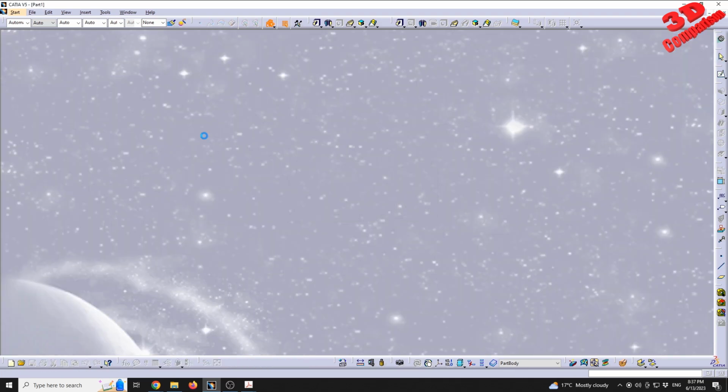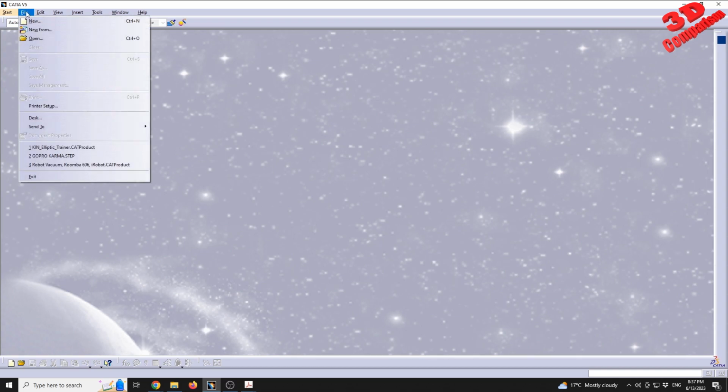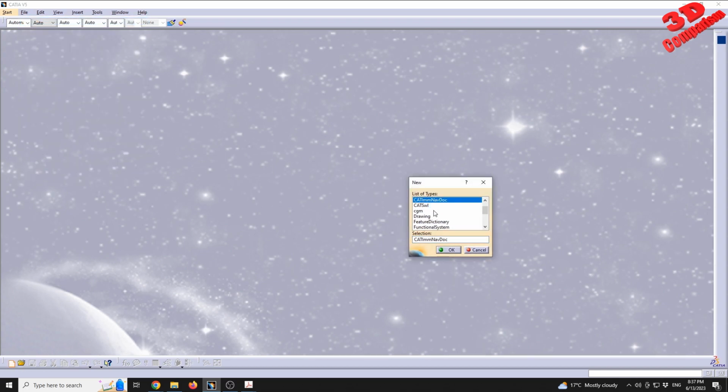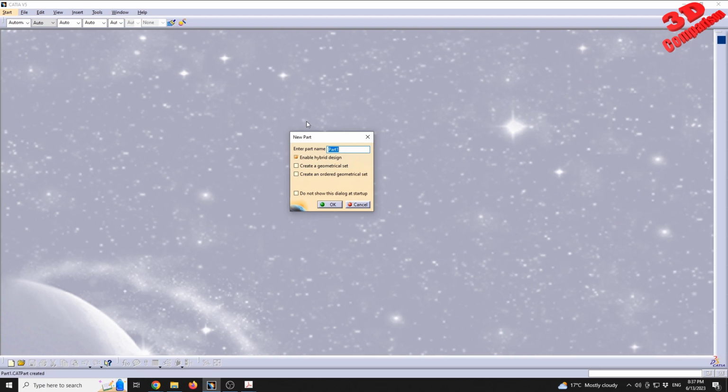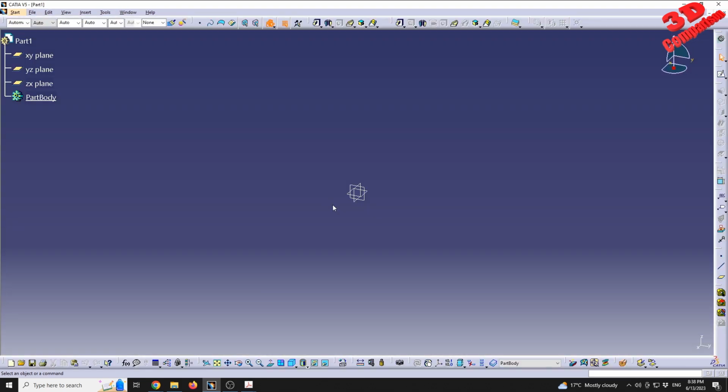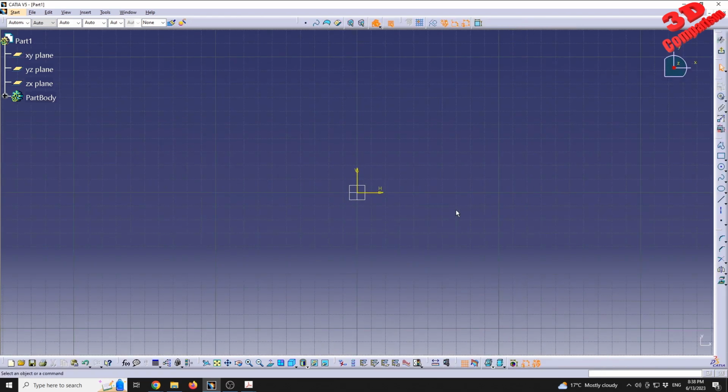We can also start in a different way. So if I go up to File, New, over here I can go for Part, and by default in Catia for the part level, so there are multiple levels like part, assembly, and there's also drafting or various simulations, they will be within the same location. So if I just create a new part like this, since Part Design was the last workbench from this category open, the software will lead me directly over here in Part Design, just like before. And over here I have the possibility again to select that and start tracing some sketches.